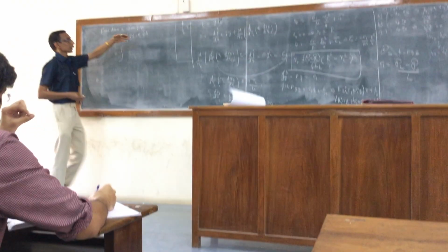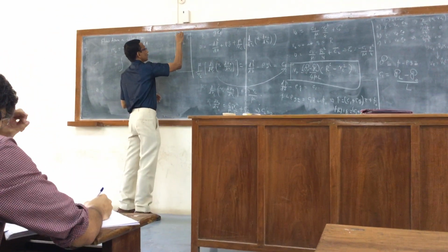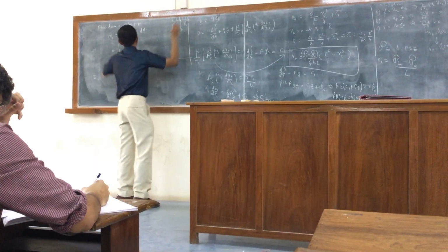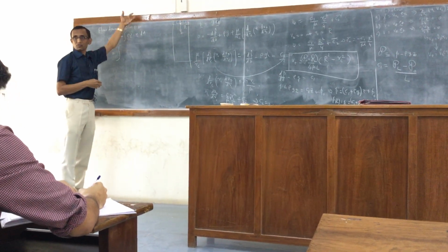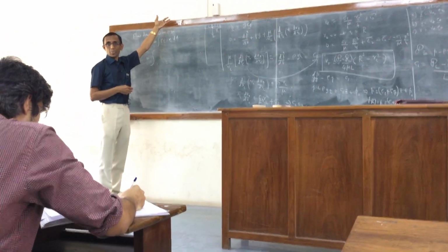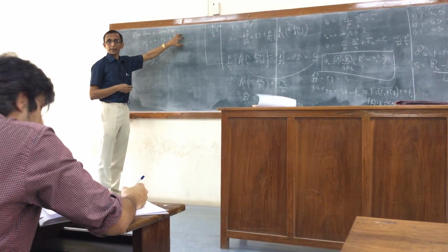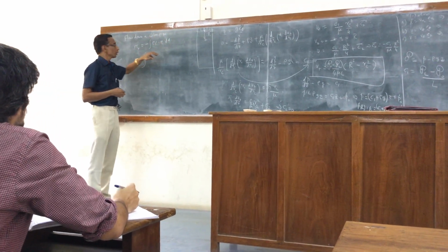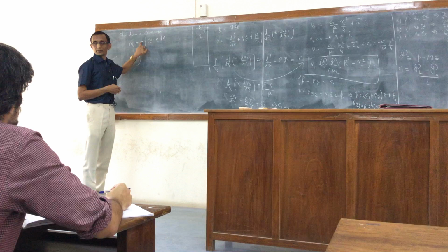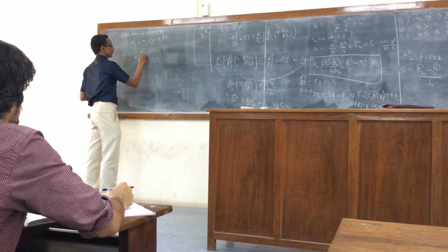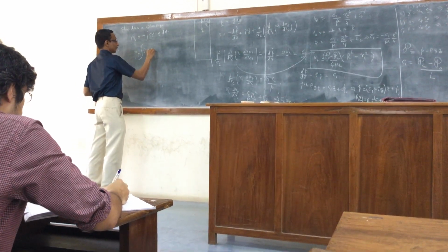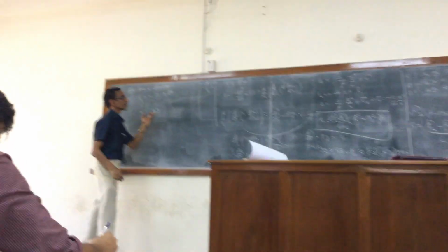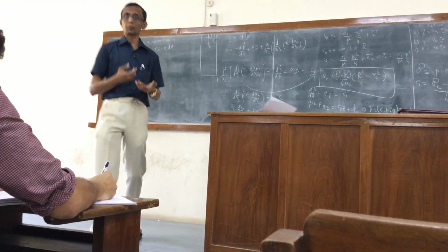So here I'm looking at the entry point. This will give me the mass efflux, rho v dot n. If we want the mass inflow, then I have to put a negative sign. So it is minus rho v_z e_z dot n, the outward normal.